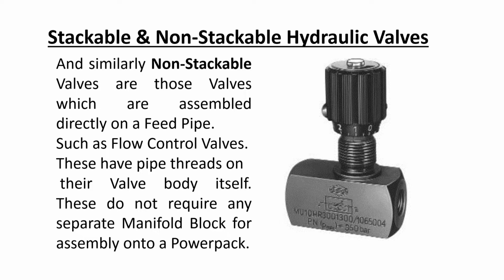Similarly, non-stackable valves are those valves which are assembled directly on a feed pipe. So these valves, such as flow control valves, have pipe threads on their valve body itself. So they do not require any separate manifold block for assembly onto a power pack stack.